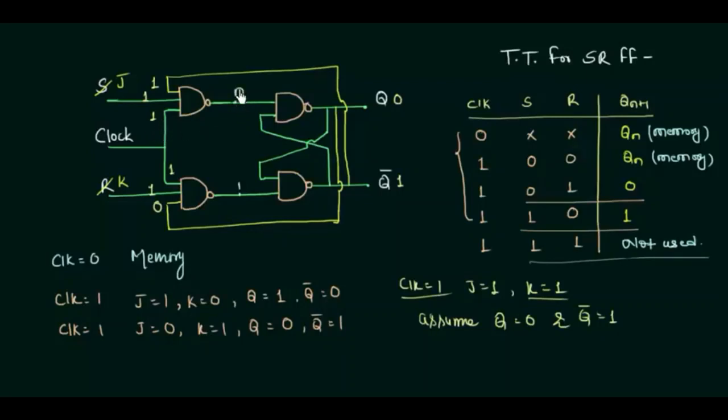So at this point I'm having 0 and 1, and 1 and 0 is 0. Taking the complement gives us 1. So for the NAND SR latch, I'm having inputs as 0 and 1, and you very well know that when this happens, the output is 1, 0. Okay, now you can see that the output is changed, so the input will also change.